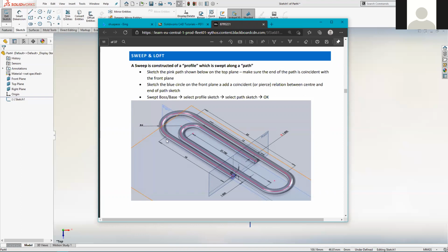The other thing I'm wondering about in terms of this shape is whether it's worth drawing a straight line initially, and then a tangent curve on the end of it, and then stopping for a moment and getting the size of those two correct? I suspect it probably is, because having drawn shapes like this before, you can end up drawing the entire shape, but the scale and size of it is entirely wrong. And then when you start adding dimensions to it, as we've seen before, the shape gets pulled inside out, and you end up with nonsense basically. So I think we'll put that first.